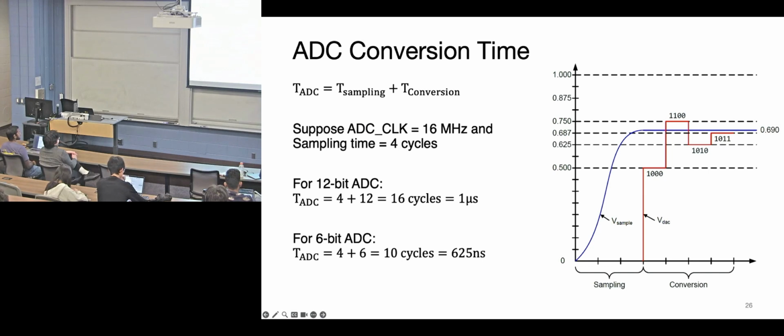It doesn't matter how long you convert for, you're always going to have to pay this time penalty. Okay? And then it says that you have a 16 megahertz clock. And how many bits is the ADC? 12-bit ADC. So in this particular case, you're going to have to do 12 successive approximations, right? You're going to have to go through this 12-bit binary search to find the value. And so then you're going to do 12 clock periods of 16 megahertz. And so here's 4 clock periods of 16 megahertz plus 12. Does that jive with what you're seeing here, what you're thinking?